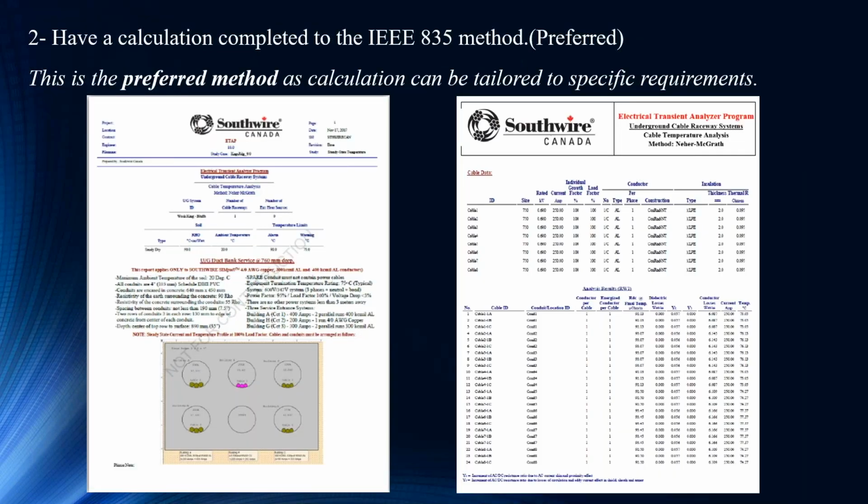So this relates to what I was saying earlier, that it is important to understand that tables and diagrams were created with certain base assumptions. Earth characteristics as well as specifications of the material used when laying underground distribution lines vary. As I said before, selection tables are convenient, but the built-in assumptions are almost always overlooked. Thus, after all these approximations are made, the variations from the actual value add up. So again, that may result in significant discrepancies and wrongly sized cables.